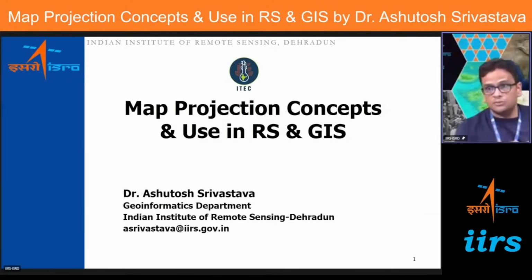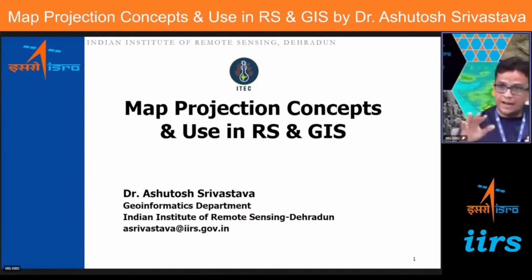But at the same time, you are comparing with satellite images. The satellite images already have the coordinate system and projection system of today's satellite image, and one you have is a scanned image. Now you want to compare both. The scanned image will not have any coordinate system. So what you will do is assign the coordinate system first to that particular image, and then only you will be able to compare. Correct? So this was another example.